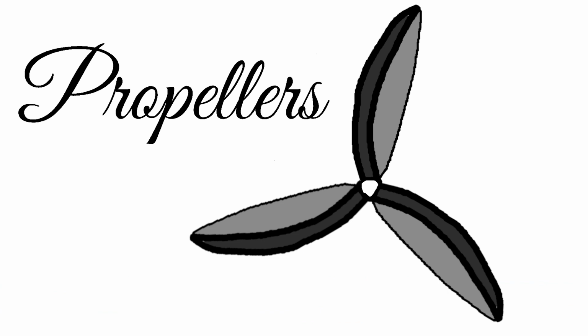Propellers. Diameter and pitch calculation. A common designation is 12 by 6, meaning the propeller has a diameter of 12 inches and a pitch of 6 inches. Propulsive thrust. Propulsive thrust is the forward force the motor and propeller produce that balances out the drag. When the total drag force and propulsive thrust are equal, the plane no longer accelerates. If this happens at max thrust, the velocity is called cruising velocity.